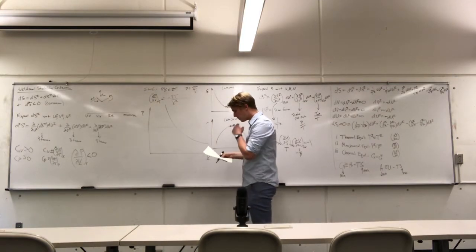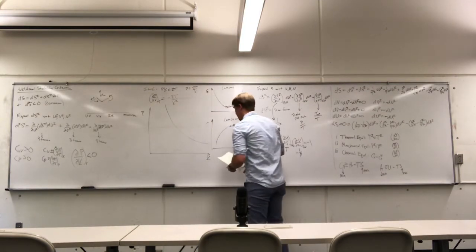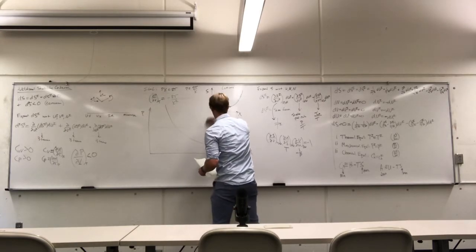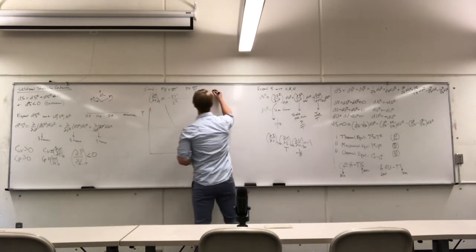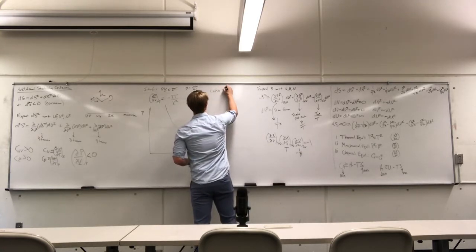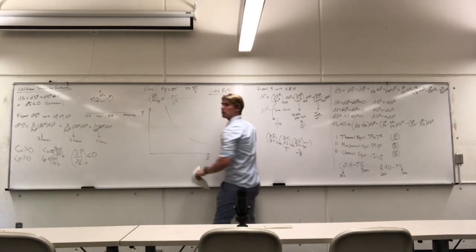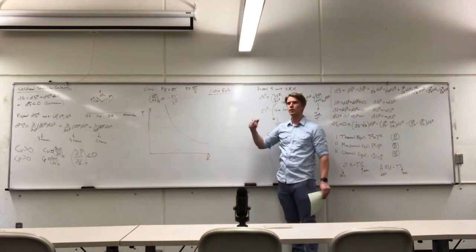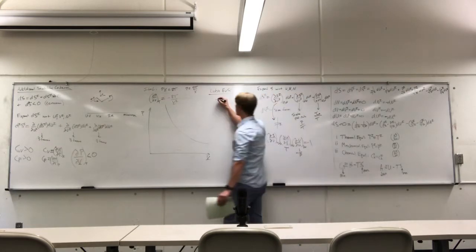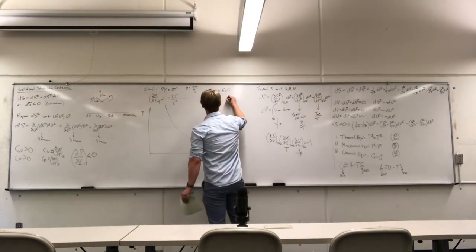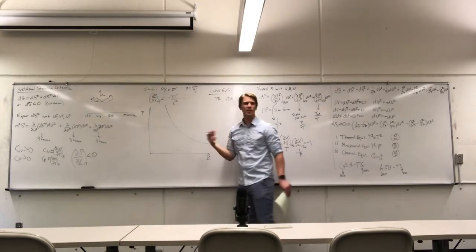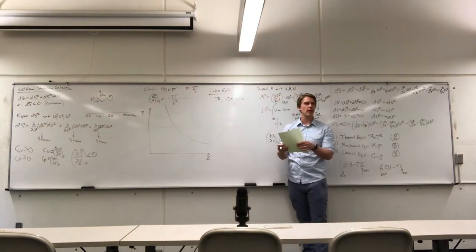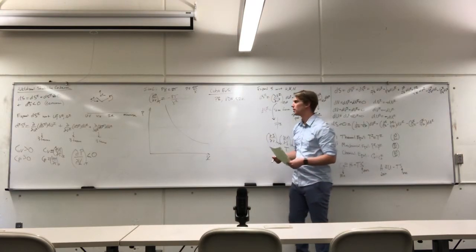Now what we'll be talking about is a class of equations called a cubic equation of state. What's an example of a cubic equation of state? Peng-Robinson is a great one. We have the van der Waals equation. We have the SRK. Those are the common ones. But there's a lot of other niche ones that are designed specifically for certain fluids. Water, for example, might have a very dedicated cubic equation of state.